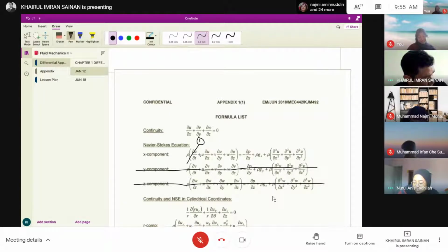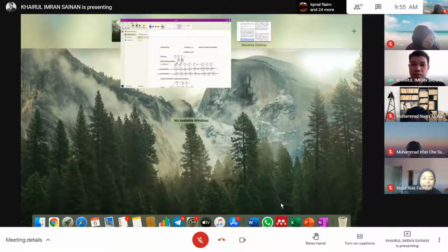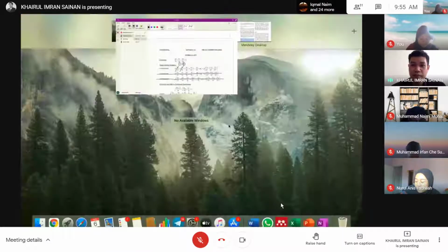U component. No, you don't cancel U. U over dx cancel. Okay, alright. So U is not cancelled out, but del U over del X cancels. Very good. Why? According to assumption number 3, fully developed, right? Yes. Very good. Thank you. Alright, next is the next term.